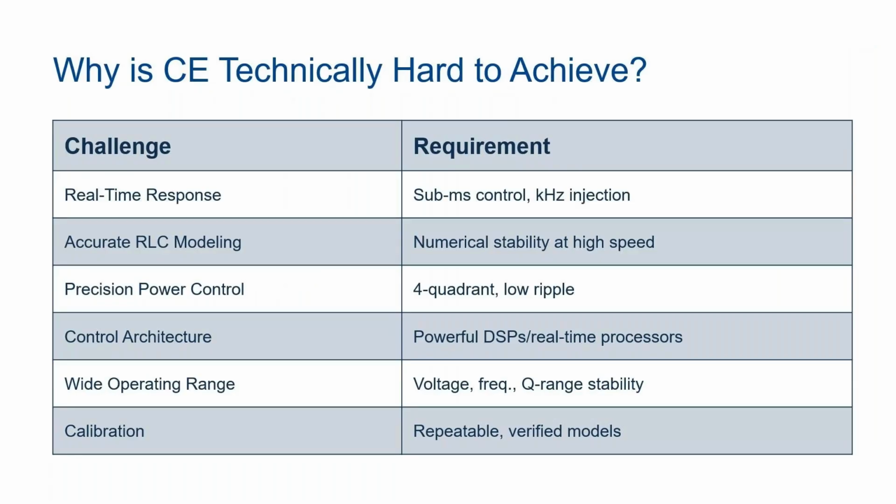Circuit emulation is not very common on electronic loads. Most electronic loads will offer things like constant current and constant power settings, where you basically control the voltage, the current, the power. CE is more advanced, so it basically simulates dynamic behavior.